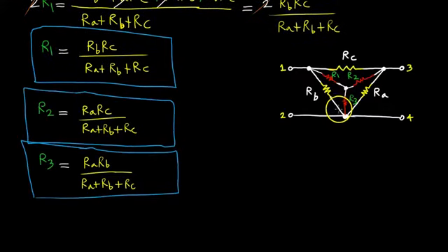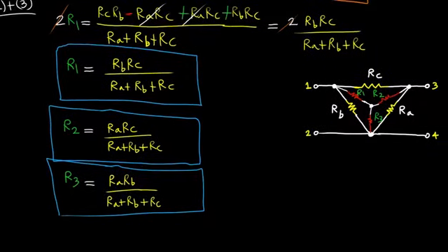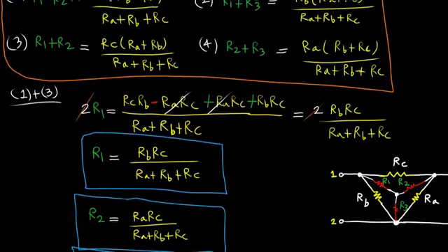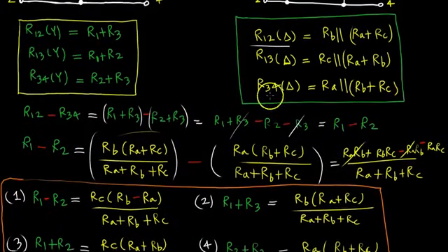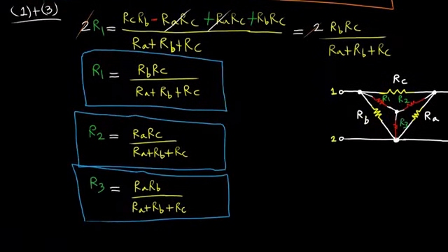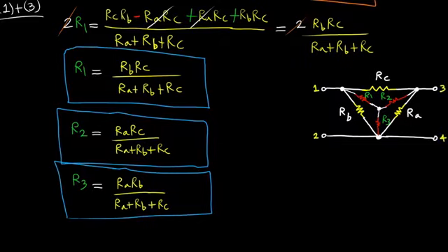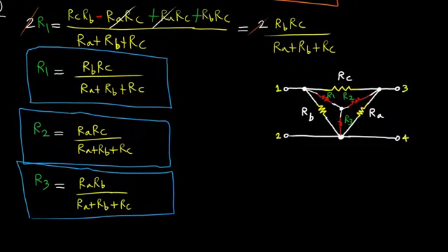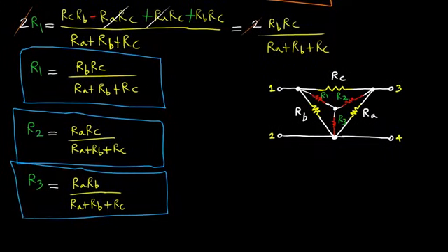Now I've summarized the remaining resistors R2 and R3 in terms of the resistors of the delta network. If you wanted to do this mathematically, you could use the equations that I showed above, and rearrange them in such a way that you would eliminate other variables and get the particular resistor that you want to find relationships for. But we can also do it a simpler way. Since we found the answer for R1, we could come up with a general rule that we could follow without having to do this every time.